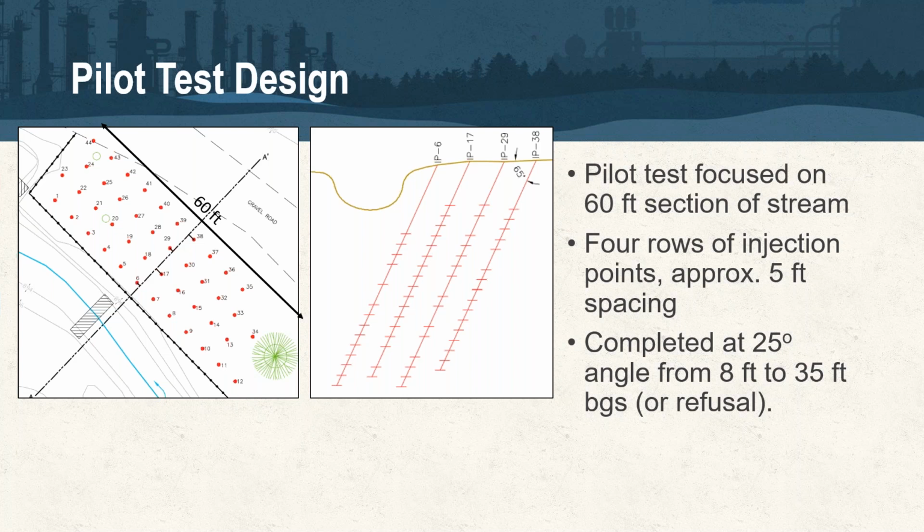But I'll give you an example of where the fixed lab that's in Denver was used in real time. I was installing a PRB recently up in the Northeast, and as we were installing the PRB, we were installing quality control wells. So we would finish a 40-foot section of the PRB, install a well on the down gradient side, sample it, and keep going.